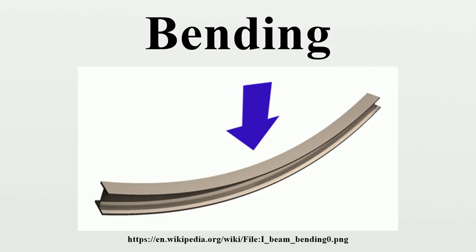For example, a closet rod sagging under the weight of clothes on clothes hangers is an example of a beam experiencing bending. On the other hand, a shell is a structure of any geometric form where the length and the width are of the same order of magnitude but the thickness of the structure is considerably smaller. A large diameter, but thin-walled, short tube supported at its ends and loaded laterally is an example of a shell experiencing bending.